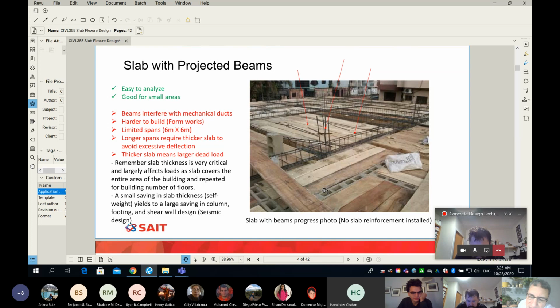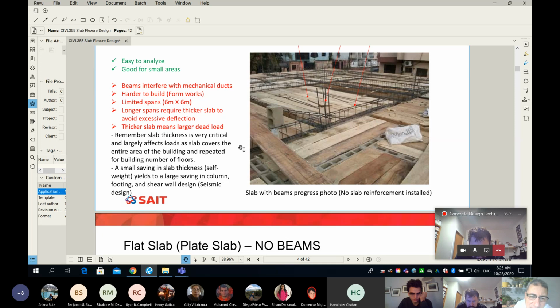So the same thing applies when seismic hits a building. If the building is light, it doesn't have much earthquake effect. If the building is heavy, then earthquake will govern. Same as our houses. Our house is made out of wood, and wood is very light, and that's why when we design residential, typically what governs is wind, not seismic. If you design a concrete building, because the concrete is very heavy, the seismic design will govern more than the wind. Anyway, hopefully I'm not going more than I should in seismic design, but here is the point.